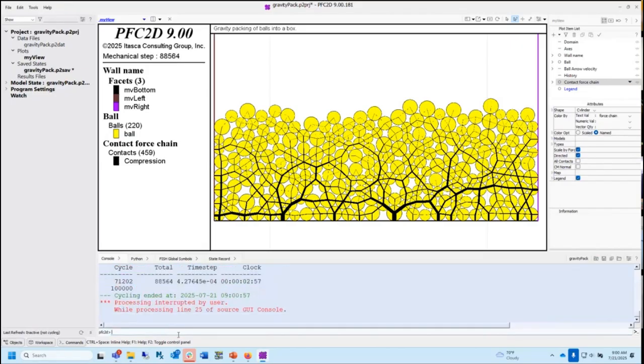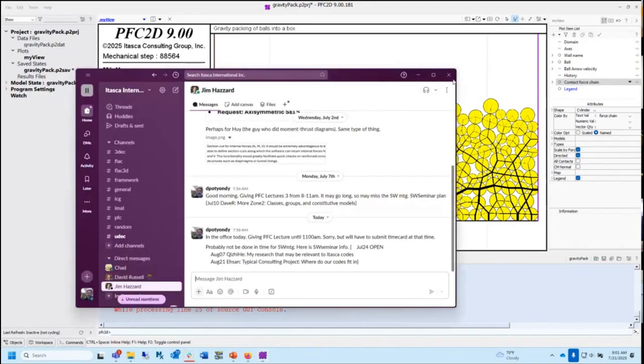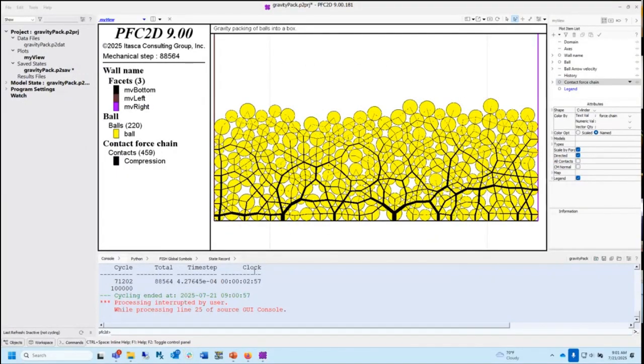I just have one question here. For example, I know the material that I am packing has a rough surface. So when I pack it, I shouldn't use a friction coefficient of 0, or if I want to reach the densest state, I still have to use a friction coefficient of 0. Well, if you want it to be like your real material, you should always use the real friction coefficient.